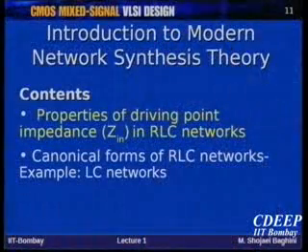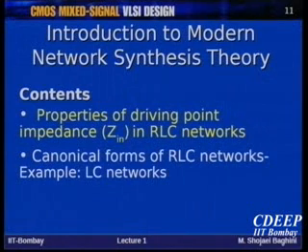First, before starting how we can use a lossless network to synthesize the transfer function: after all, we want to design a filter, and designing a filter means H(j omega) or H(s) is given to us, and we want to design this filter. So we should realize this H(s). We realize this H(s) using passive components L and C, and then we will make a two-port. There will be one input port and one output port. These input and output ports will be terminated by resistors.